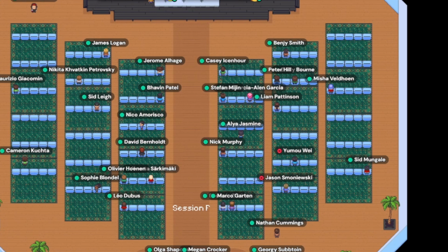Excellent. So there's one question coming from Luis Garcia. How would you input an OpenMC heating CSV output into a MOOSE simulation? Is it using the heat source module? So that's a good question. So we have different ways of doing this. If you want to do that OpenMC simulation separately from the MOOSE simulation, you can input the volumetric heating source.